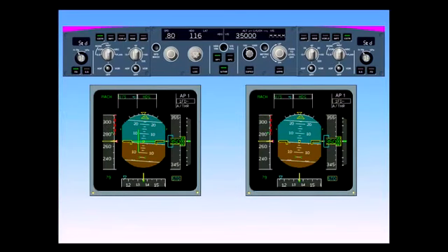Flight Director 1 is on. The crossbars are displayed on PFD-1. The FMA on both PFDs indicates 1 FD for Flight Director Engagement Status, meaning that only Flight Director 1 is on. Note that the symbols and FMAs for Flight Director 1 are displayed on both PFDs. Also note that Flight Director 1 push button illuminates in green on the EFIS control panel.